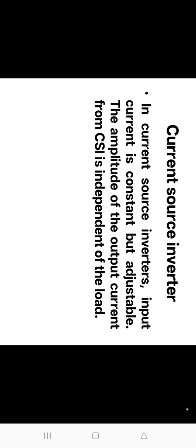The four series diodes effectively prevent the capacitors from discharging through the load in the interval between inverter commutations. IGBT pairs T1, T2 and T3, T4 are alternately switched to obtain a nearly square wave load current. As usual, the triggering frequency of the IGBTs determines the output frequency. The circuit behavior during the commutation interval is highly load dependent. The operation of this inverter circuit can be divided into four operating modes.